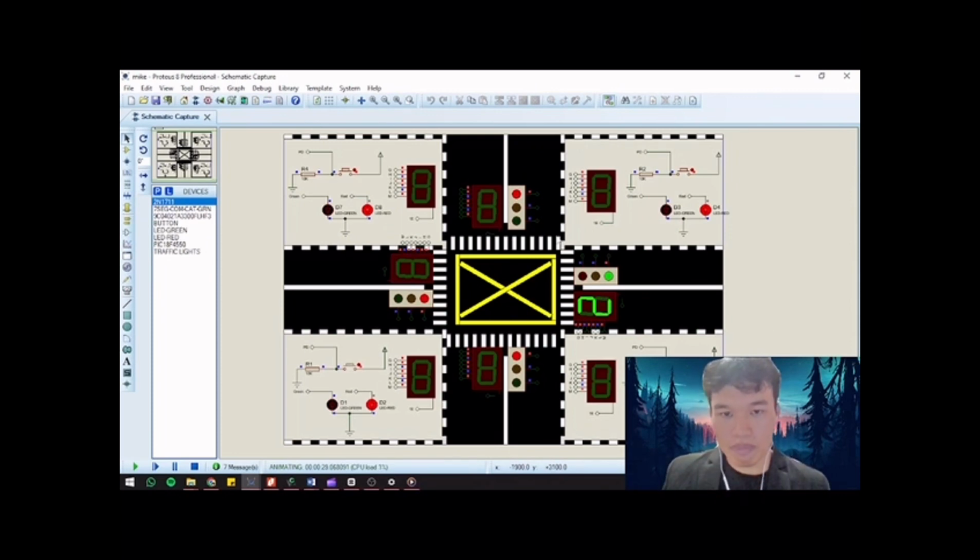To interrupt all this traffic, the pedestrian system must be activated. To activate the pedestrian crosswalk system, all the traffic LEDs will have to turn red, and the seven segment of the traffic must be 0. When the pedestrian crosswalk system is not activated, it will turn on the red LED to indicate it is not safe for the pedestrian to walk.